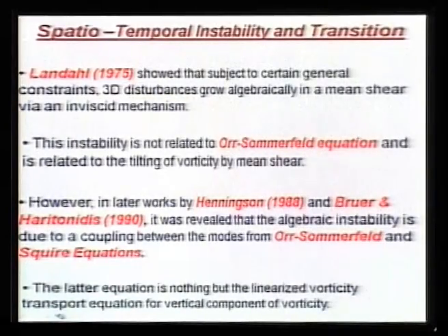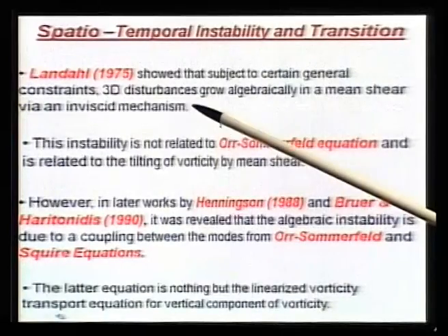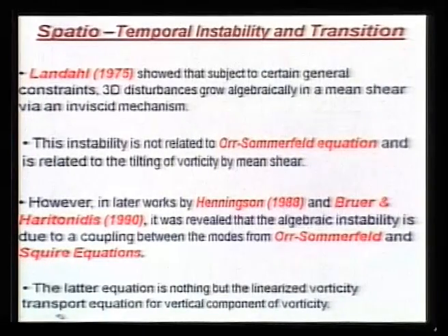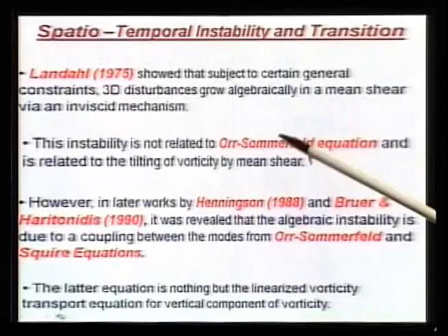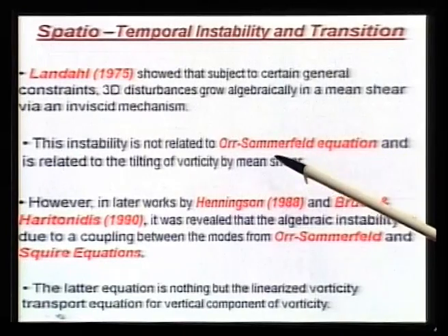Landau actually discussed an inviscid mechanism, where he found that 3D disturbances can grow algebraically in time, also in space. And this mechanism of algebraic growth is distinctly different from the viscous instability given by the Orr-Sommerfeld equation.